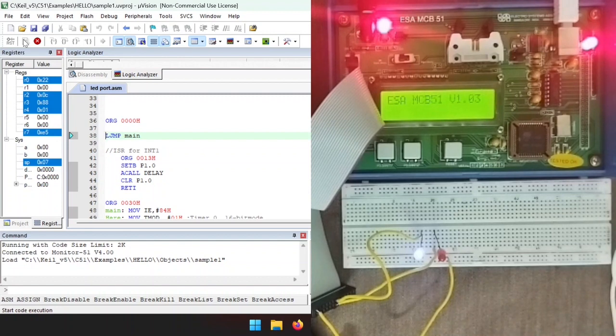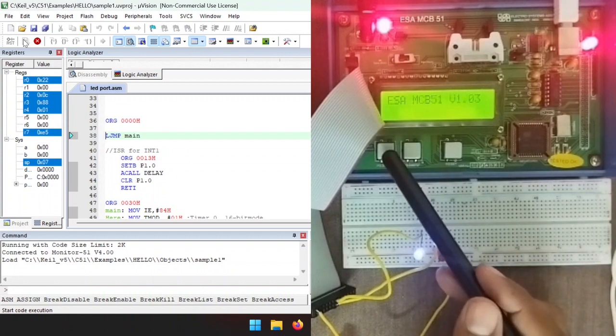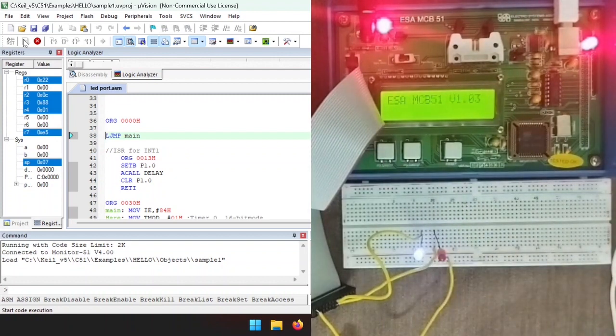While in the theory class I explained the priority register, right? The first priority is given to interrupt 0, after that timer 0, after that interrupt 1, after that timer 1, after that the serial port. Now try to shift the routines. Change the priority and see how it works, and we can check it in the hardware programs also.